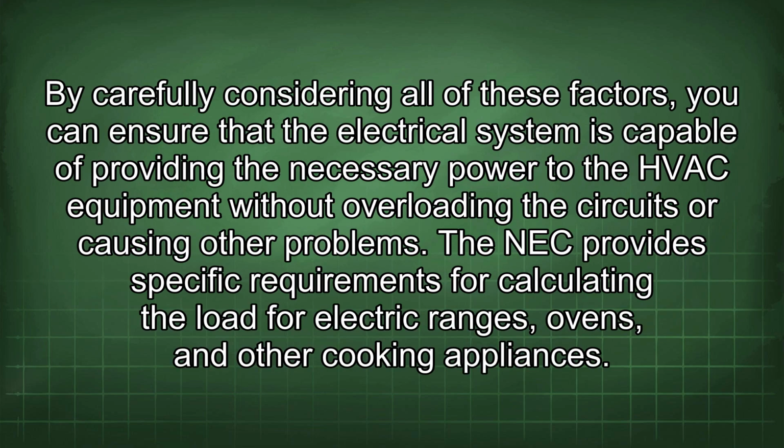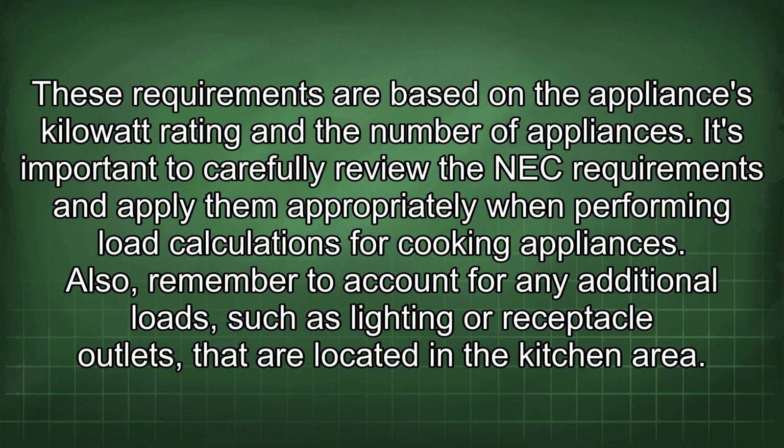By carefully considering all of these factors, you can ensure that the electrical system is capable of providing the necessary power to the HVAC equipment without overloading the circuits or causing other problems. The NEC provides specific requirements for calculating the load for electric ranges, ovens, and other cooking appliances. These requirements are based on the appliance's kilowatt rating and the number of appliances. It's important to carefully review the NEC requirements and apply them appropriately when performing load calculations for cooking appliances.